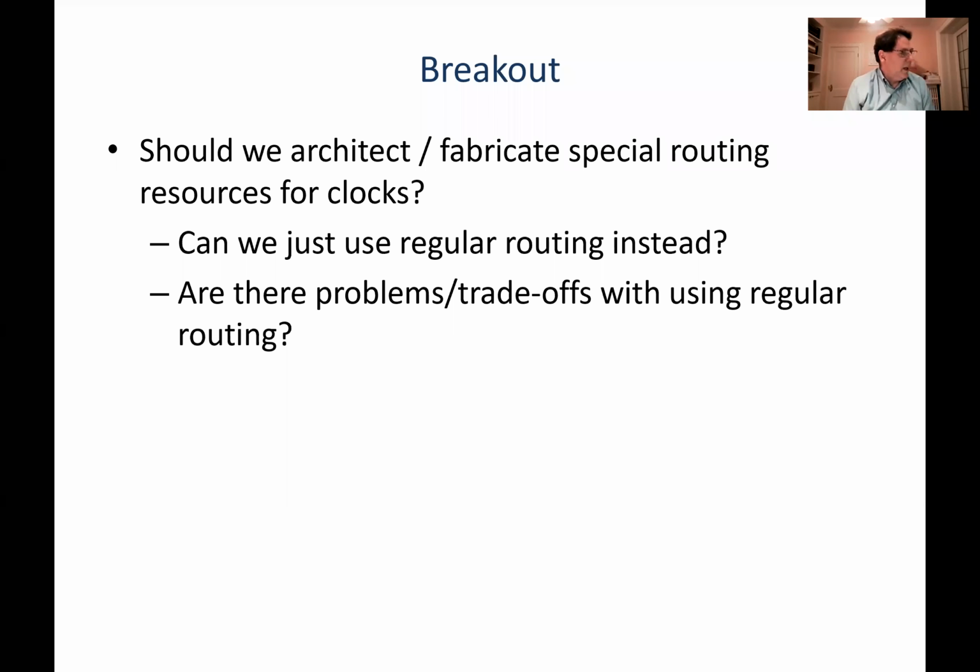Dedicated blocks handle delay, skew, generation. Yeah, that's a good point by Michael. So we also need dedicated blocks to generate clocks. We could have those, PLLs and DLLs. They can drive regular routing, but they also can drive these dedicated networks. So we have a logical place where we know what some of the sources will be for these dedicated networks, which makes them a bit easier to architect.